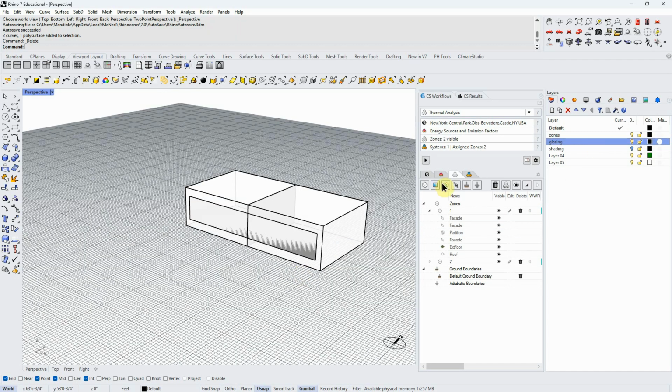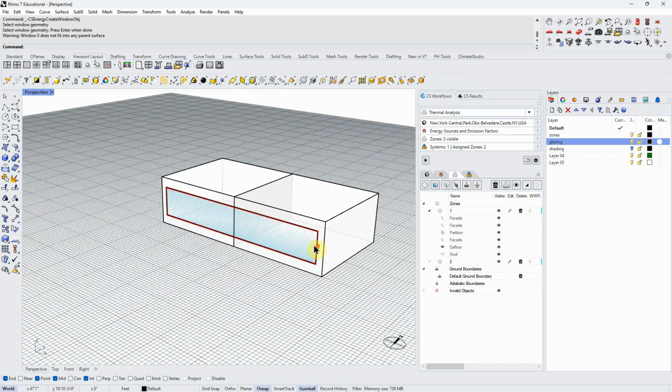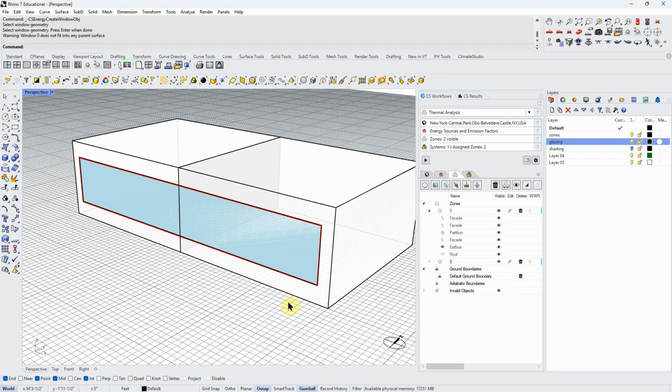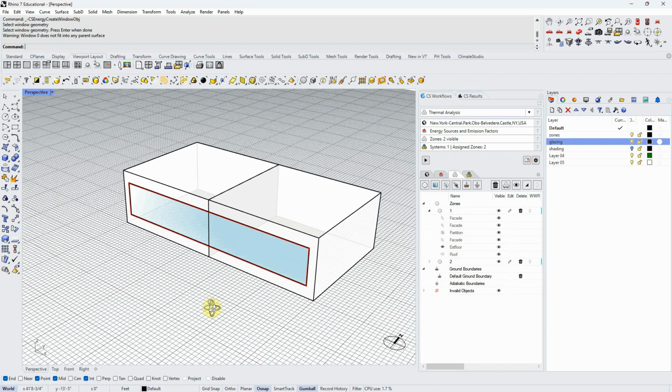You'll see that when I add that here. You should have already done this one, I'm just trying to review. The problem when I add this is that the outline turns red, which means it's not working. That's because we're going across two zones. And that could make sense, right? If this had a different number of people in it and needed different heating and cooling, or had a different facing, then this glazing is going to have different properties.